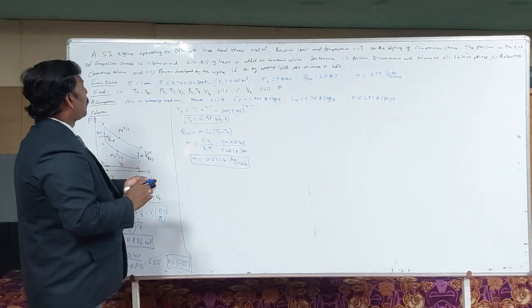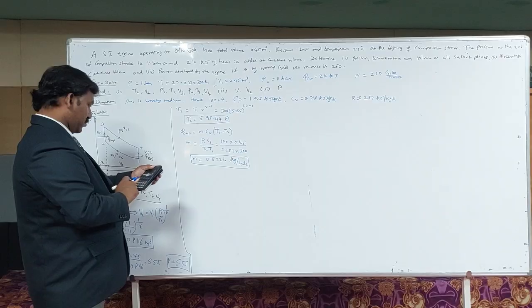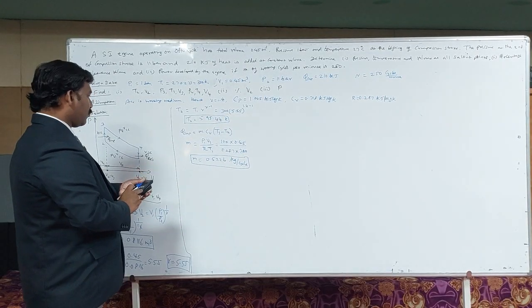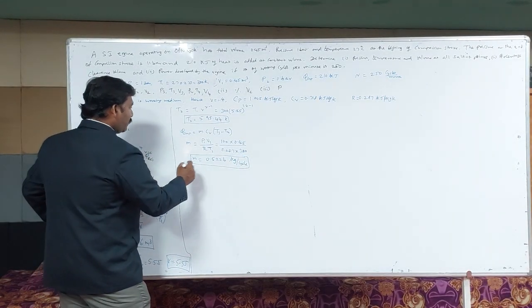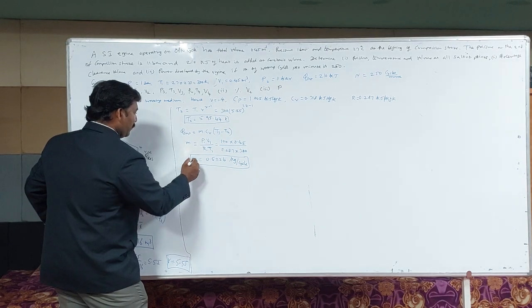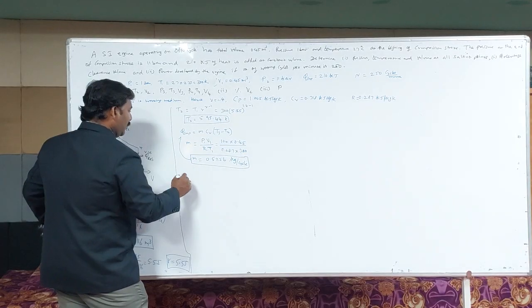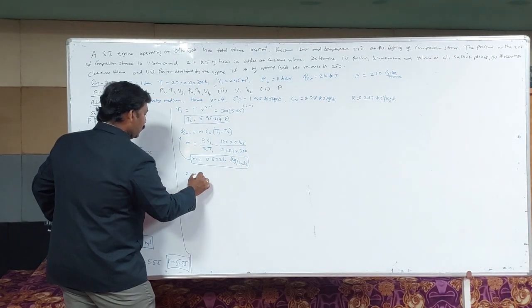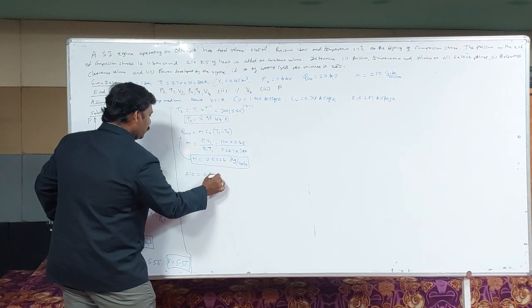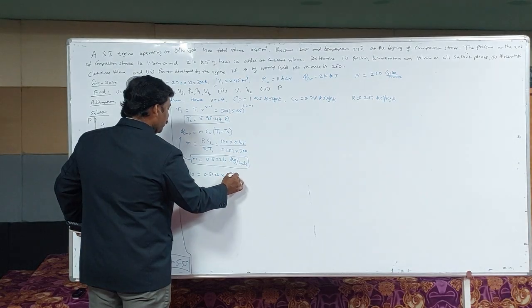All right. So 0.5226 kilogram per cycle. And we have to now find out T3, substituting the mass flow rate in the heat supplied equation. You get 210 kilojoule is equal to 0.5226 kilogram per cycle into Cv value 0.718.